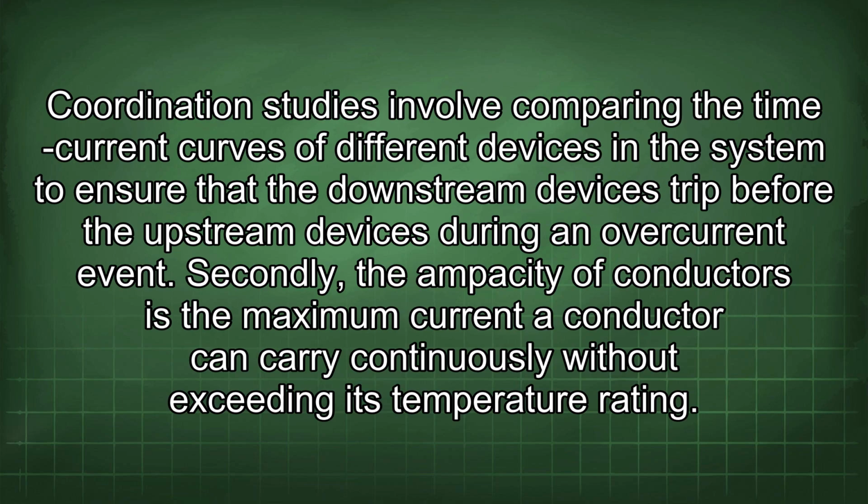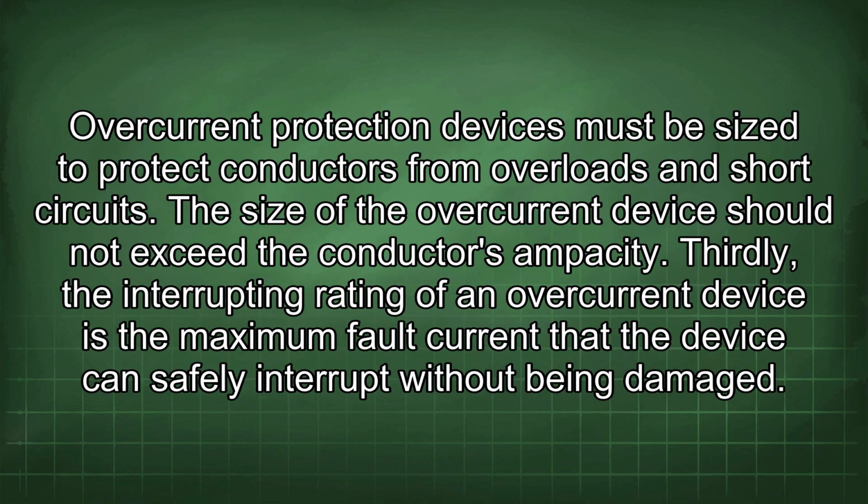Secondly, the ampacity of conductors is the maximum current a conductor can carry continuously without exceeding its temperature rating. Overcurrent protection devices must be sized to protect conductors from overloads and short circuits. The size of the overcurrent device should not exceed the conductor's ampacity.